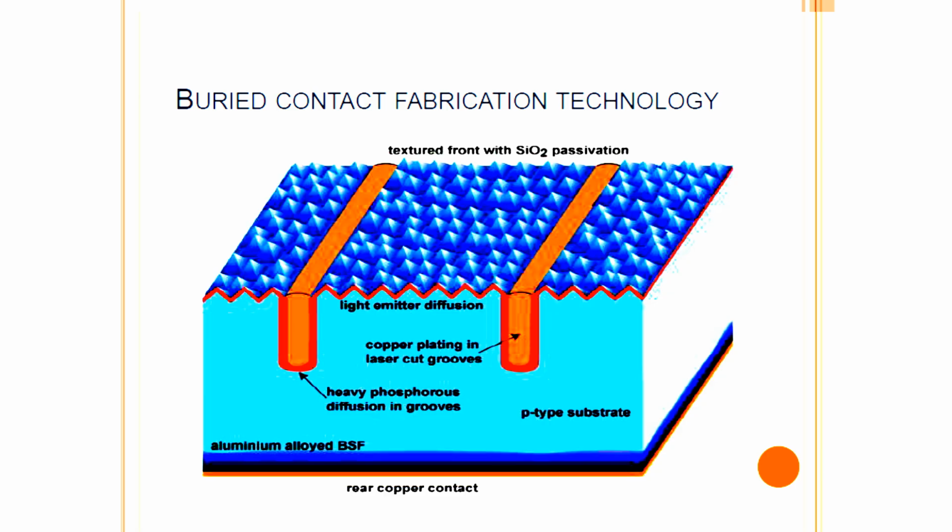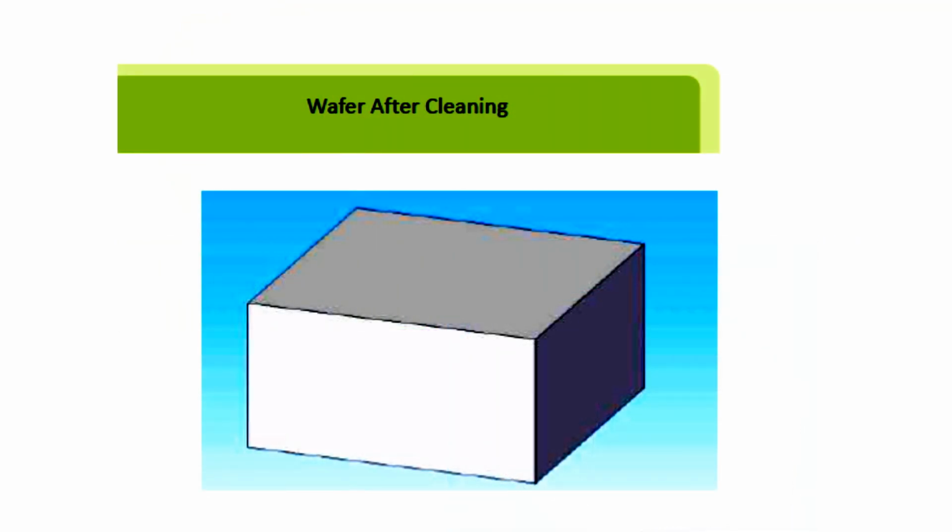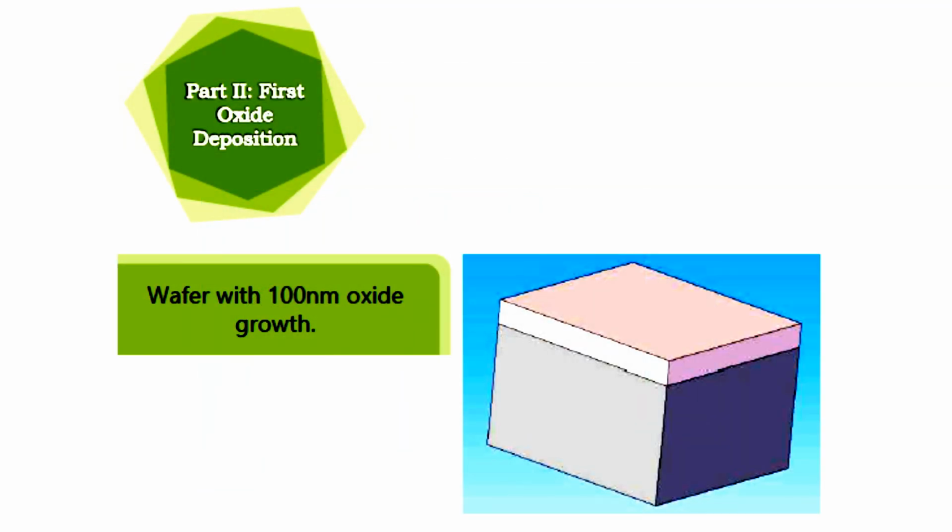Let us see briefly buried contact fabrication technology. In this we have the wafer before cleaning, wafer after cleaning, wafer with 100 nanometer oxide growth.